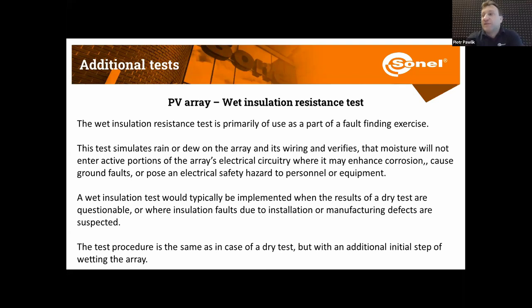The next of the additional tests is the insulation resistance test in wet conditions. Generally we perform it the same way as the regular tests of insulation resistance. However, we need to spray our test site with water to create some moisture, and then we perform our tests.